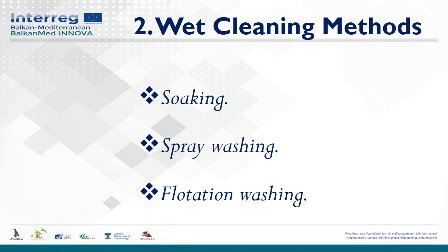Spray washing is a method used for a wide range of raw materials. Factors affecting the qualitative performance of these methods are the volume of water used, its temperature, the time used for the cleaning process, and the size or volume of raw materials. The volume of raw materials is very important because if their sizes are small, the cleaning process will be more effective than in large materials, which need to be rotated so that the whole surface is presented to the spray.